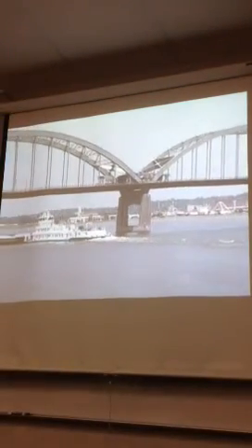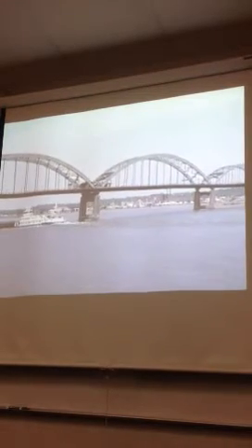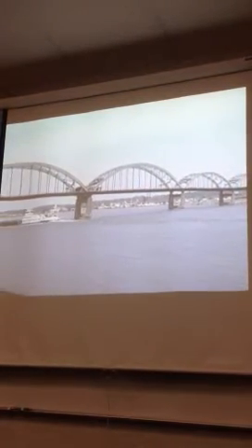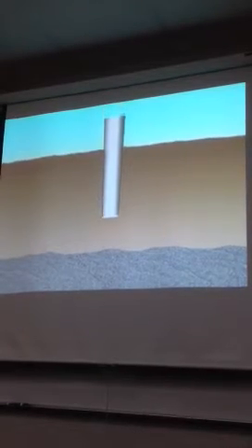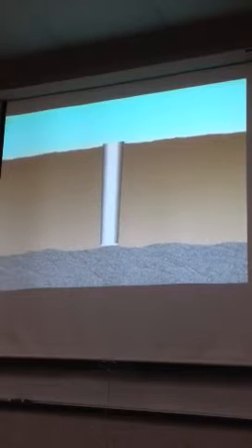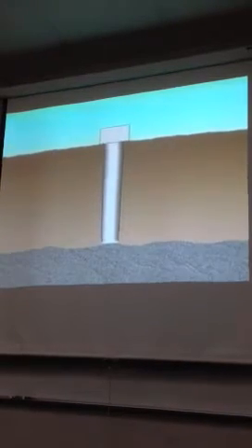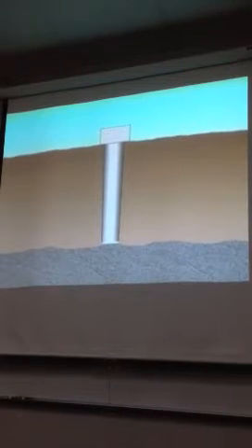But for structures like bridges, where the soil is wet or sandy, pile foundations are often used. On these, piles or posts are driven into the ground until they reach solid soil or bedrock. This keeps them from moving or shifting. Footings are then attached to the top of the piles.